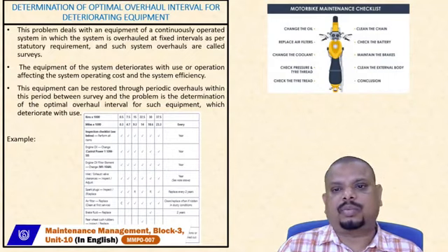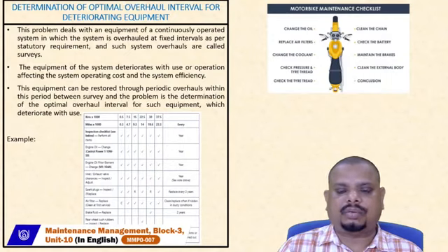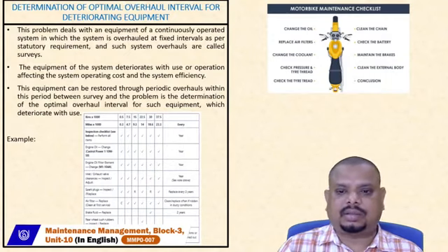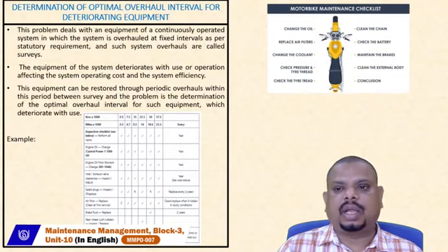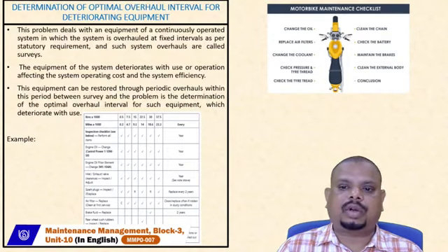So let's take the example of a motorbike maintenance checklist. First we have to change the oil. The next is replacement of air filters. Then change the coolant in the case of engines. Check the pressure and tire treads. Check the tire treads and, if required, go for replacement. The next important part is clean the chains, then check the battery levels, then maintain the brakes, then clean the external body, and finally go for conclusion.